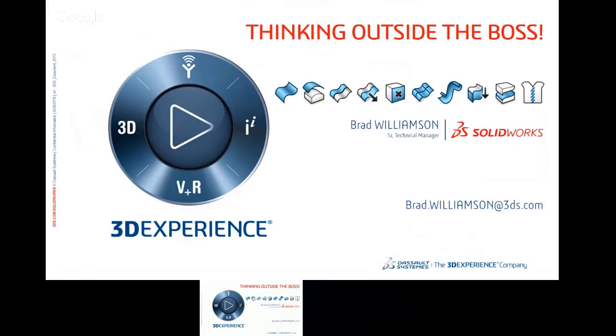But the other point, as he was saying, was even at Makani, tangency was fine for aerodynamics. The only thing that curvature continuity does for you is it looks really nice. As far as the wind going over it, it doesn't need to be that smooth. It's one of those things that people in air and car are used to, they want a nice smooth body.